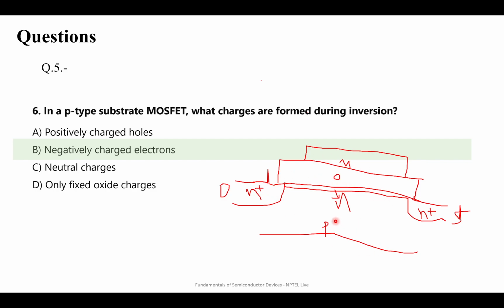So this is how a traditional planar MOSFET works. For years, this has been the structure of a MOSFET. Now there are new designs of MOSFET coming in, such as FinFET and Gate All Around FETs. But traditionally, this has been the structure of MOSFET, and due to this inversion layer, only your conduction is happening. When this inversion layer is not formed, your transistor is off.